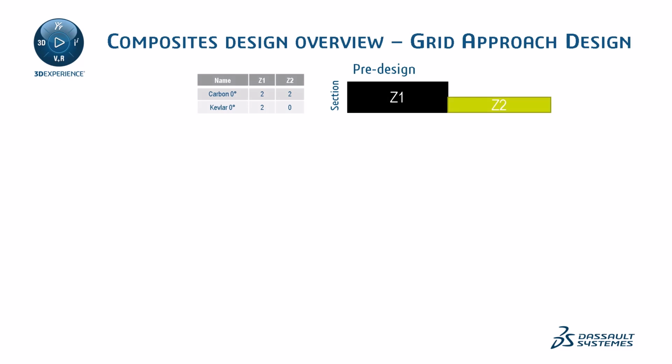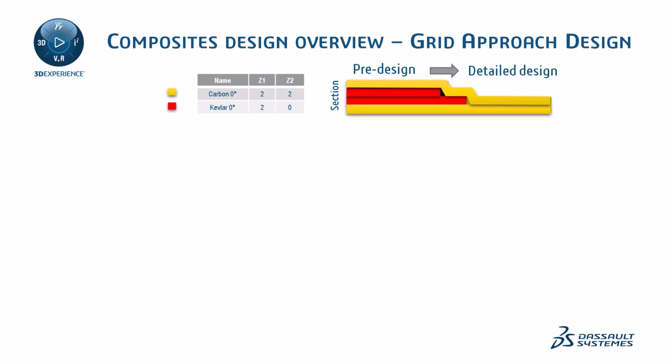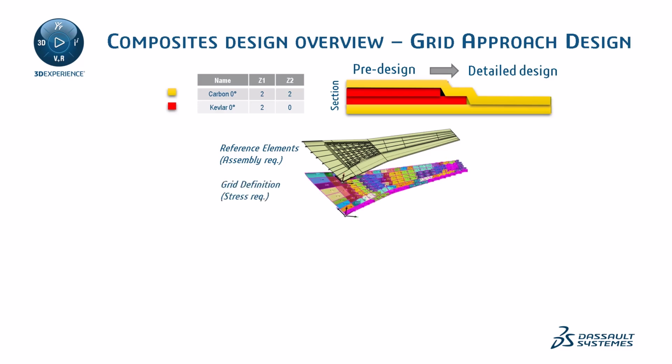The grid design method is used to design composite parts, in the context of an assembly, by referencing structural elements to integrate into the design and analysis process. The designer must determine which structural elements to use in the grid panel, and apply composite laminates to the resulting grid definition. This preliminary design/sizing view is then turned into a detailed design by managing the plies sequencing details and the virtual stacking before the actual creation of the plies detailed definition.